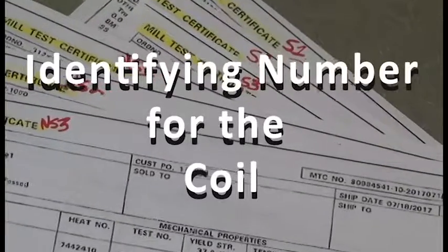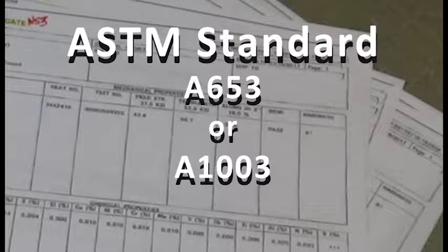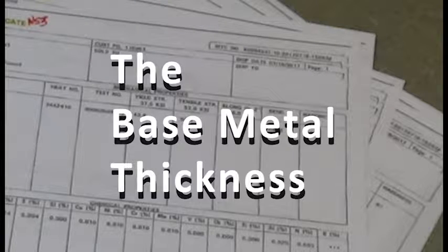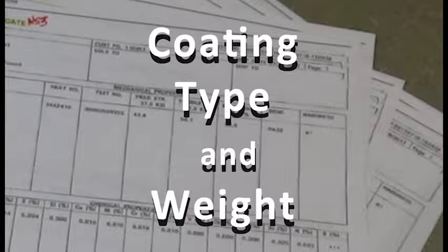An identifying number for the coil, the ASTM standard it meets, either A653 or A1003, the base metal thickness of the material, yield and tensile strength, the coating type and coating weight applied to the material.